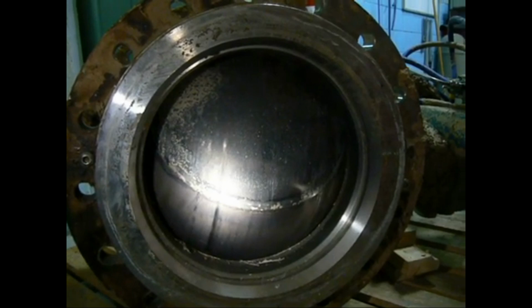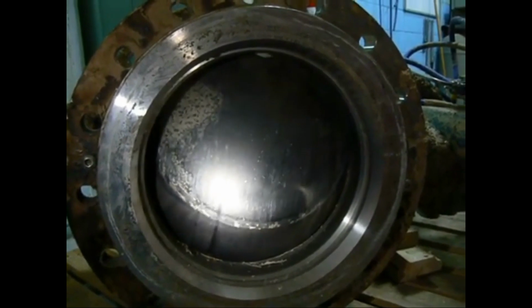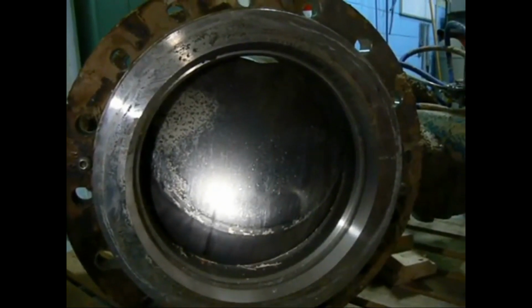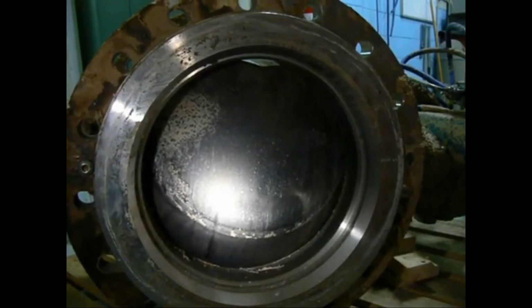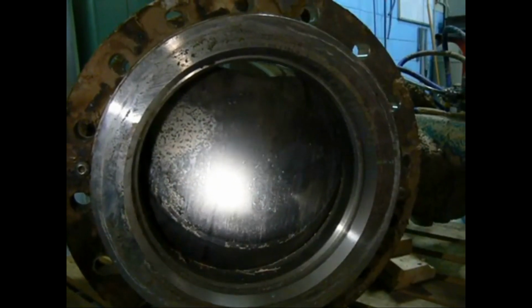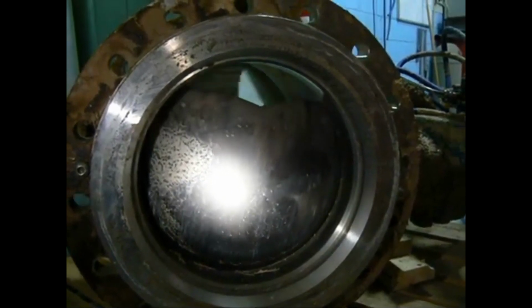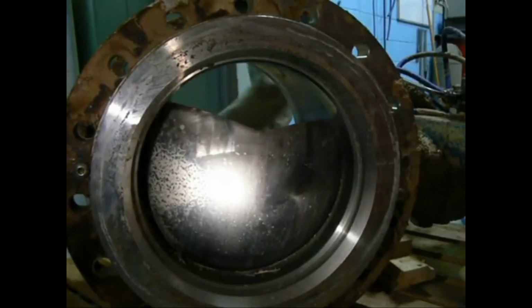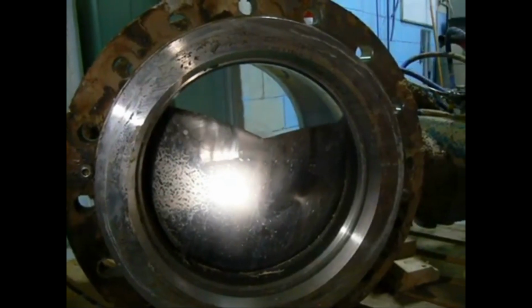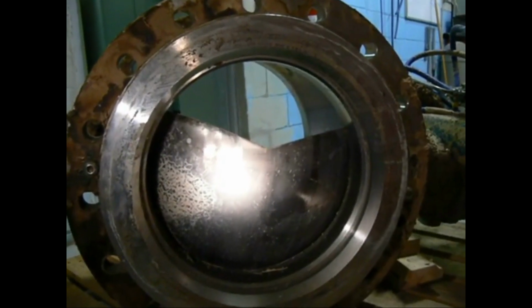You can see here it's a ball valve, and the quality doesn't look very good because you can see some of the scoring going on here. So here we're opening up the valve itself. As we're opening it up, we should be seeing a nice gradual opening, and you can tell that this is not happening. We're having a lot of jerky motion because there's a lot of friction within the valve itself. You can see right there as it opens up. I'll let it go a little bit longer.